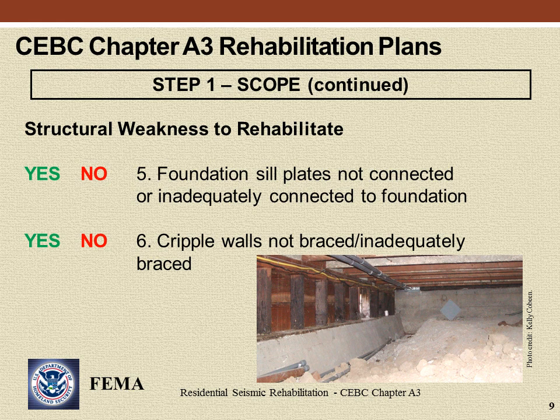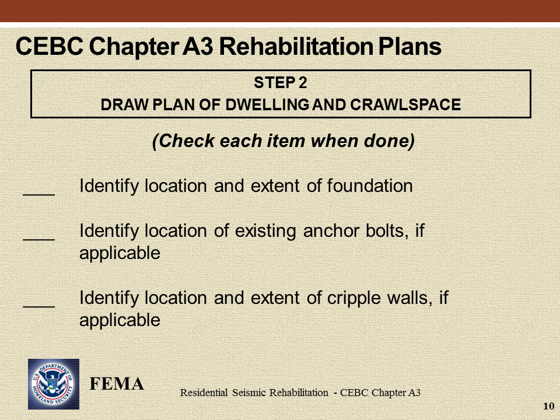In this photo, foundation sill plates are not bolted to the foundation. Exterior walls are poorly braced with straight sheathing. For this dwelling, an answer of yes should be provided for items 5 and 6. This is a candidate for foundation anchorage and cripple wall bracing.